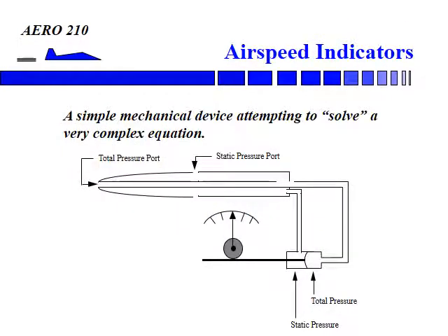More commonly, instead of using a manometer, we hook up those ports to a pressure gauge, a differential pressure gauge, and we calibrate it in airspeed. So we know that the pressure changes with velocity squared, the difference between those two, which would be dynamic pressure. Look again at Bernoulli's equation to satisfy yourself that the difference between total pressure and static pressure is the dynamic pressure. That's proportional to velocity squared, and all we have to do is change the gearing mechanism in the gauge and the calibration of the dial so that it reads in velocity rather than pressure.